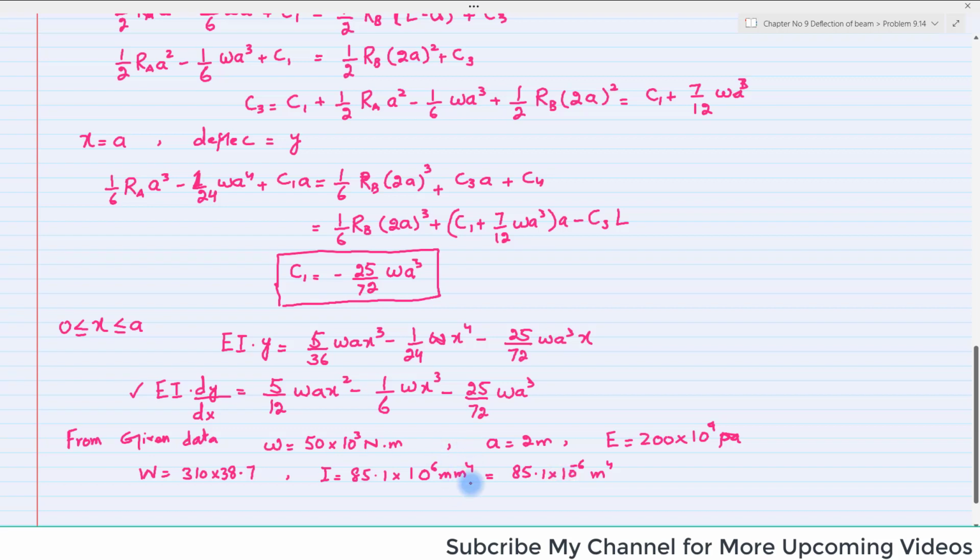Clear? Again, there is EI, so it is better to multiply E with I. EI is E into I, equal to 200 into 10 raised to power 9 multiplied by 85.1 into 10 raised to power minus 6, so it will be equal to 17.02 into 10 raised to power 6 Newton meter squared.